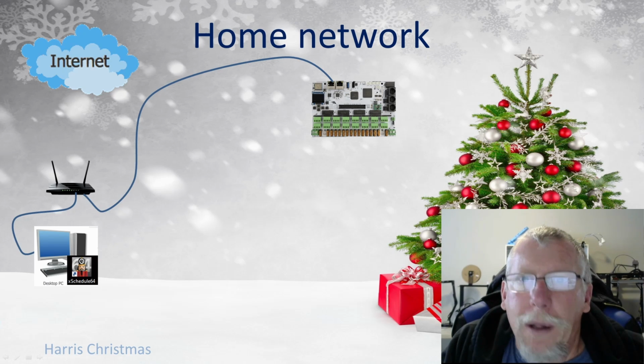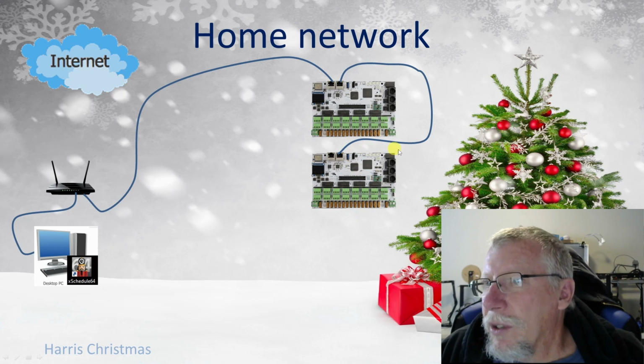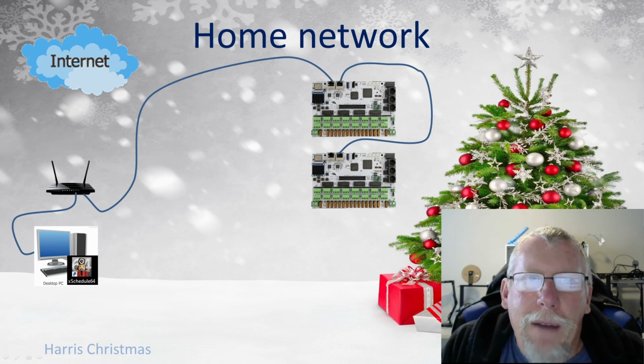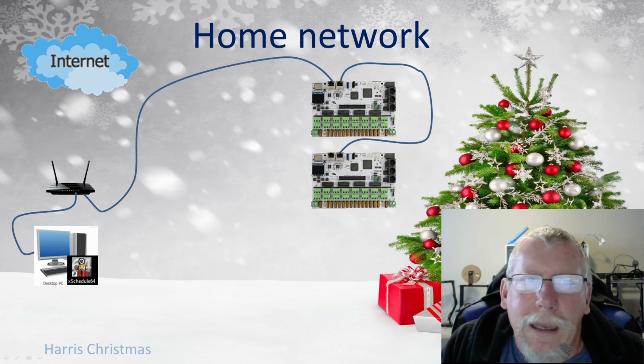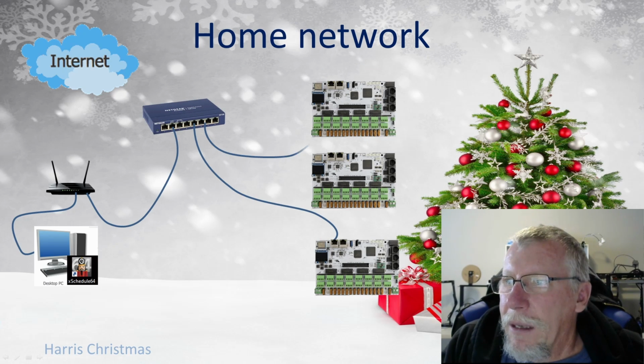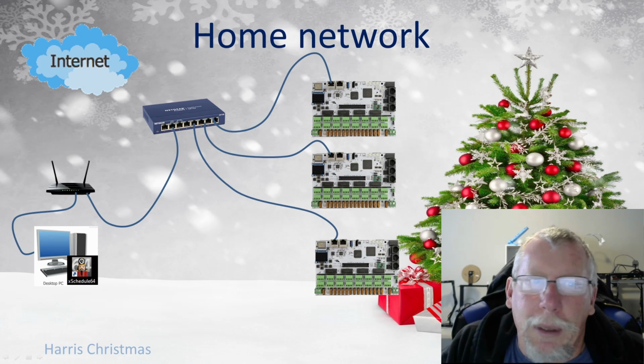If you have 2 to 4 Falcon controllers, you can daisy chain them like this, and then just do one to the other. If you had another one, you could just connect that over to another one down below. If you have much more than 4 controllers daisy chained like this, it could cause some lagginess. If you have multiple controllers or controllers other than Falcon controllers, then you can add a switch like this. Now this will work with any E131 DDP type controller, and the number of controllers that you can connect this way is almost limitless. In all the configurations shown, you would have to use xSchedule for the player.